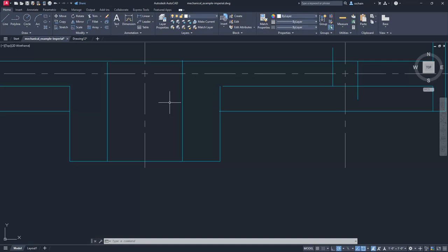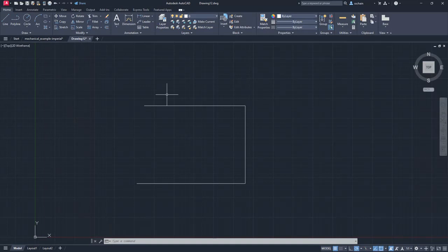For example, with a drawing already open that contains objects, from the ribbon, Draw panel, select line. Hover the cursor over part of the object. Both a marker and tooltip appear. In this instance, it is the endpoint of a line. Note that the marker will change based on its location on the object. For example, a center or midpoint appears differently than an endpoint does on the same line.